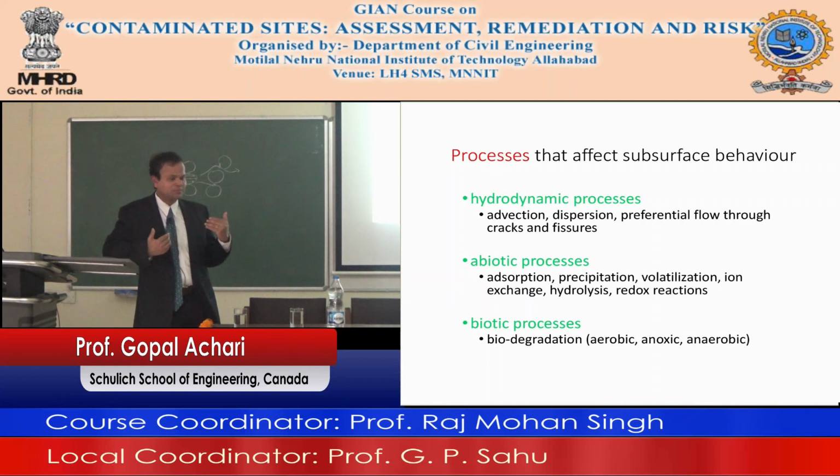Because you might find that some of the stuff you put in the place has volatilized and gone. The lighter fractions have volatilized and gone. There might be some things that, because of geochemistry, have precipitated out. They might have undergone hydrolysis. A whole bunch of reactions might have taken place. So the contamination happened like 20 or 30 years ago, and they put something in the ground, but when you come back after 20 years, it's a different thing.